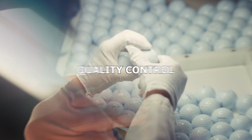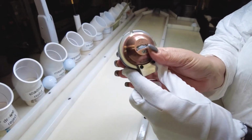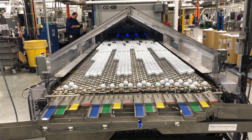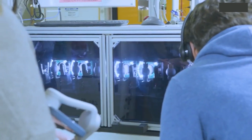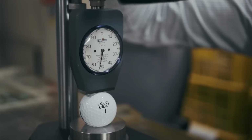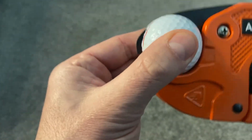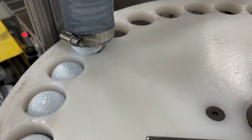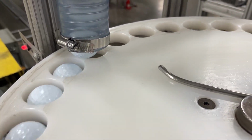Quality control. Quality control in golf ball manufacturing is rigorous, involving various tests and inspections to ensure compliance with standards. X-ray inspections and compression ratings. Three-piece balls undergo X-ray inspections to ensure the centers are perfectly round. Compression ratings measure the resilience of compression-molded wound golf balls, though these ratings do not apply to two-piece balls. Instead, two-piece balls are evaluated using a coefficiency rating, which measures the coefficient of restitution by comparing initial and return speeds after the ball strikes a metal plate.